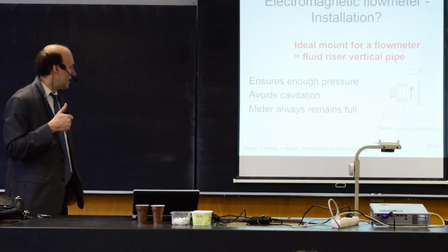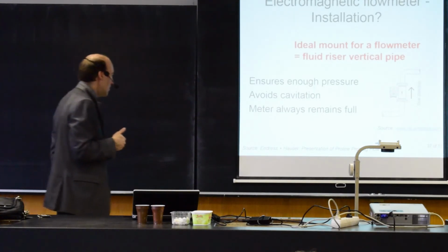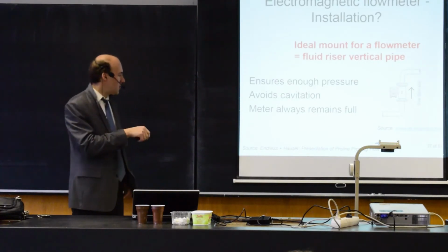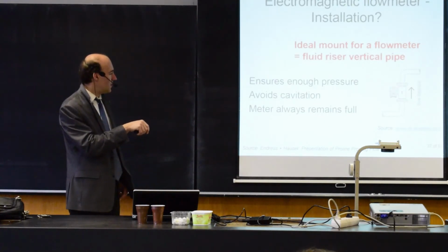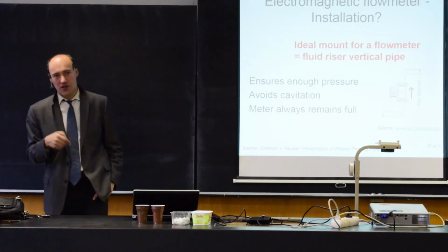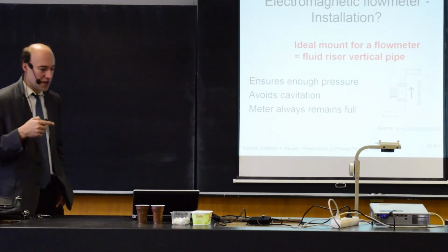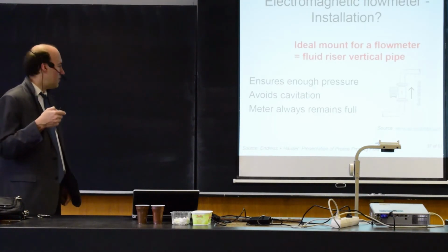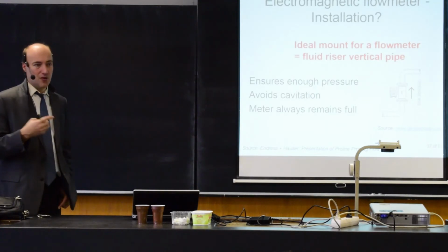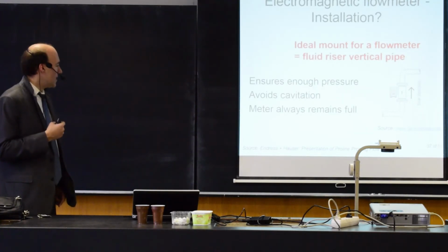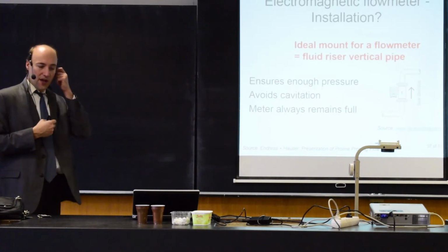It ensures you that you have enough pressure so that this is full at all times, avoids cavitation, which means that when you decrease the pressure, you may create bubbles, and it makes sure that the meter remains full at all times.